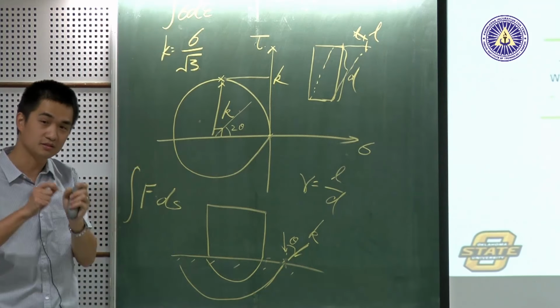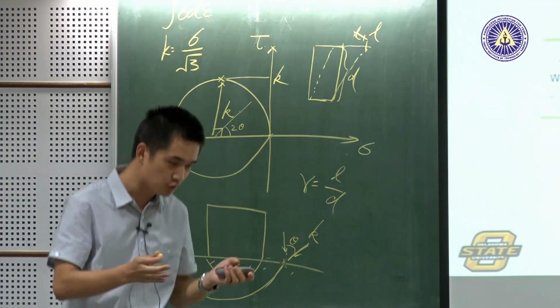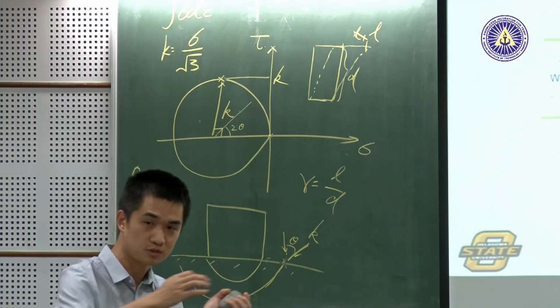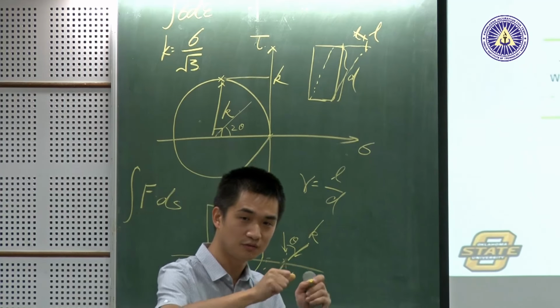Okay? So then what does that energy contribute to? When something deforms, sometimes we feel the heat, right? If you bend a steel, it has strain. If you keep bending it, we will feel the heat at the deformation point. That's because when deformation happens, this relationship contributes to energy dissipation. Energy finally becomes higher temperature, okay? That's why sigma times epsilon contributes to the temperature increase, okay?